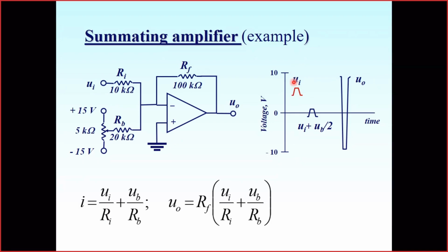Over 10 volts, it already goes to saturation. You understand there that my base will be amplified, and this small oscillation will be amplified too. But on the background of this big base, this amplification will be very teeny. I couldn't get a good amplification, because if I used a high amplification to see the details of this small changing useful signal, it goes over the saturation, and I will not get anything useful.